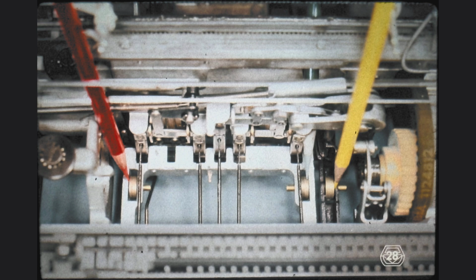During a particular printing operation, those latches which have been pulled forward by the lugs on the interposer are latches which, for the upcoming character print operation, are not used by the output mechanism. This means they have literally been filtered out. Only the latches that remain under the bail are the selected latches. They will be pulled down by the cycle bail, and they will be used to perform the character selection. This whole procedure is called negative logic or reverse logic.